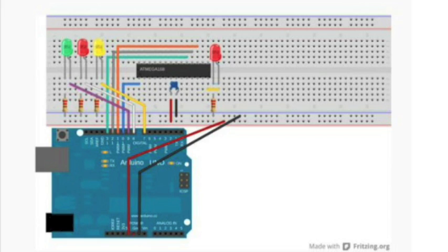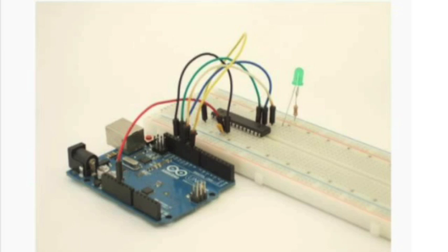At this point, you've flashed Arduino ISP into your Arduino. You've hooked these up to your target AVR on the board. You're ready to go. In reality, it'll look a little something like this. Here it is on my breadboard with a bunch of lines hooked up. This is not super special, but I promise you it works.